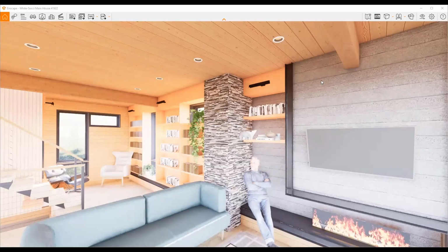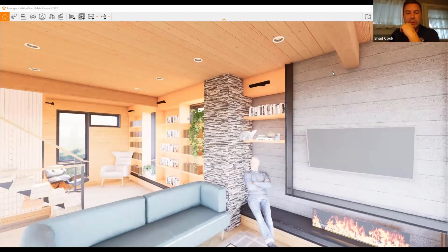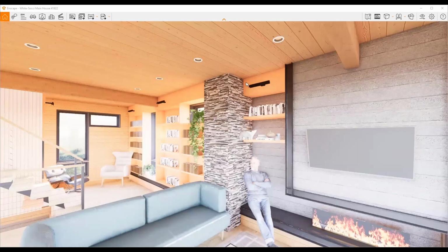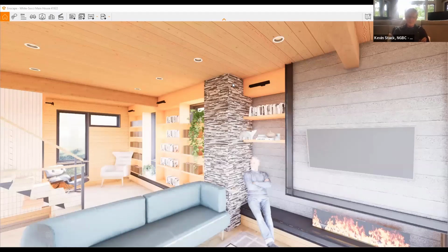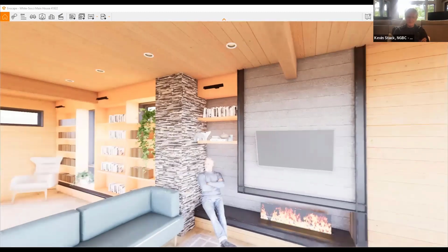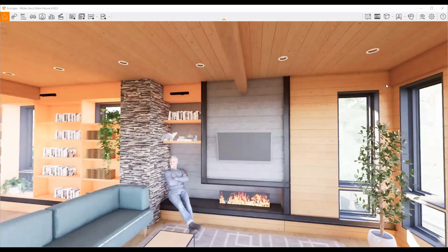Would it be able to step back into this space, since this is all pretty much open framing behind here as well? Or is that jog back in this space not really too feasible? I guess it all depends on how that stone wall is framed and how much room is actually in there to work with. So right now it's not framed, so we have the ability to frame it to meet the intent of the size of the ductwork. I just see going from LVL to LVL, stopping over that fireplace is a potential issue, but that's not an interior design issue either. If anything, I would probably carry it all the way across to the corner, although it's not my preference aesthetically. But if this is essentially open, just as a soffit. There's also no actual flue or fireplace mechanics in here at all. So this is really also an open framed space.